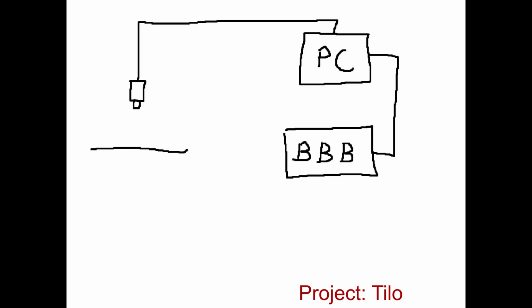Let's call them PRUs for short. Explaining the PRUs necessitates another digression. The Beaglebone Black is running Linux, and the Linux version it runs is not real-time. This means that processes can be, and are, swapped in and out of memory in order to give other processes some CPU time. This is not optimal.